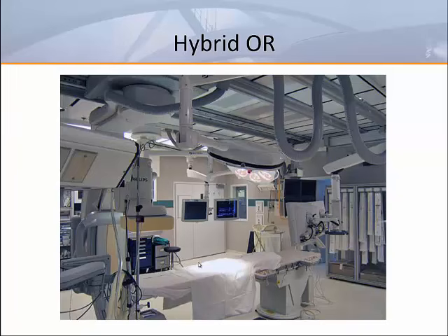While the 2014 edition of the guidelines does not set a minimum square footage, it specifies a minimum clear floor space of at least 650 square feet for new construction and 600 square feet for renovations. Required ceiling heights will vary depending on the brand or model of imaging device, but should be at least 10 feet high. Successful installations have been achieved, however, with as little as 750 square feet and 9-foot ceilings. However, it can prove difficult to accommodate future equipment updates and/or upgrades.